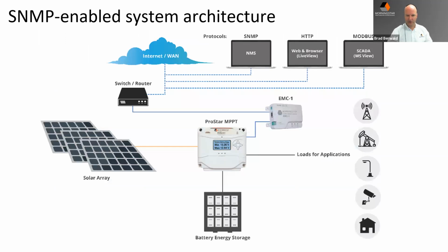So with that, we support a variety of industry standard protocols, Modbus kind of being the standard, and what a lot of the SunSpec was derived around for inter-device control. And also we support SNMP, and this is a more recent addition in just the last couple of years to our communications options. But the reason we added this was because we found that with a lot of wireless communication and connectivity, simple network management protocol was already being used by a lot of these customers to collect data regarding the connectivity of their telecommunications equipment.